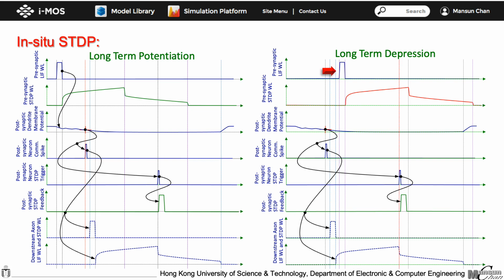As the input pulse arrived late, the feedback pulse will appear in the first half of the STDP waveform generated. Due to the high voltage of the STDP pulse, M1 is strongly turned on, and a high reset voltage is applied to the PCM cell to increase its resistance.